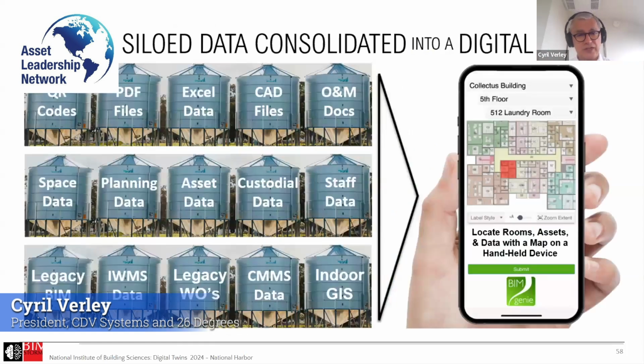And for those projects that have existing data, Onuma System allows the consolidation of a variety of data platforms to be brought into this single data. So we would always tell our clients, don't try to recreate Revit models from existing buildings. That's horribly inefficient. The better mindset is use what you have. If you've got CAD or PDF or JPEGs or PowerPoint, whatever they are, that can be brought into this digital twin also. It may not have all the information that a data-rich model would have, but it's a great start.